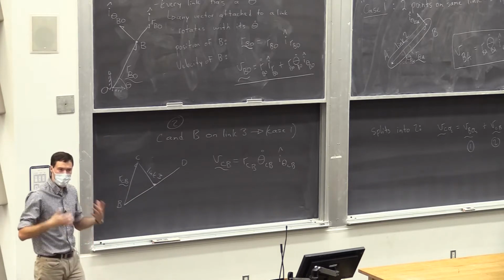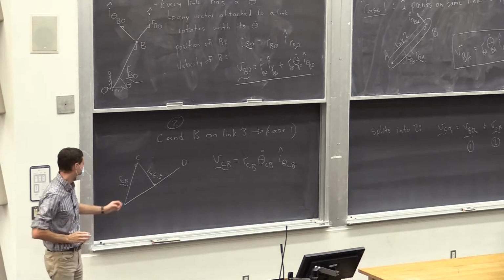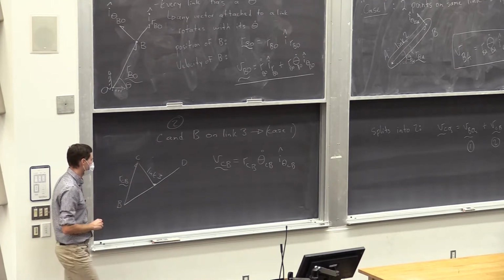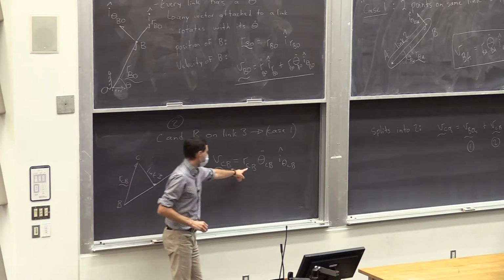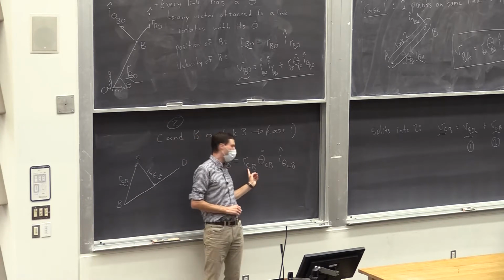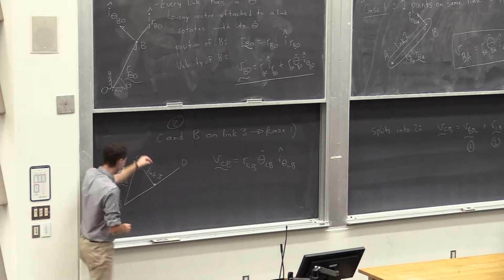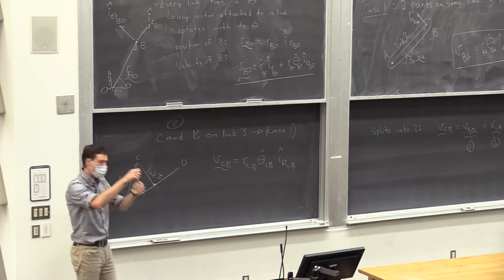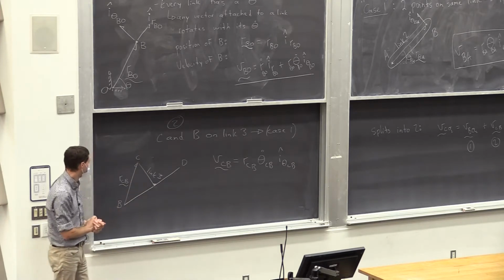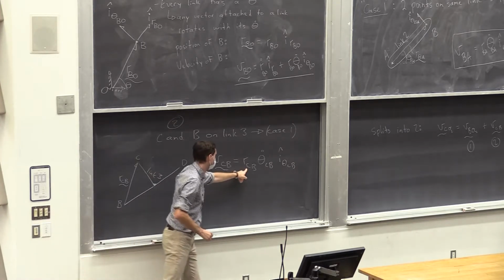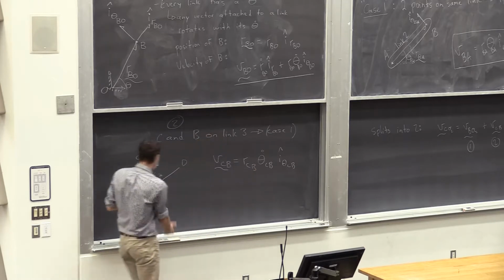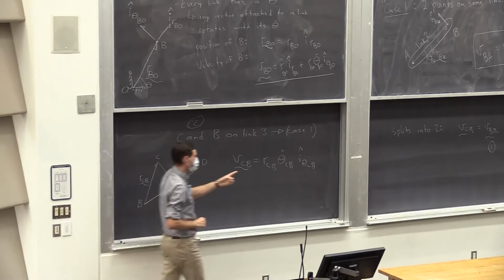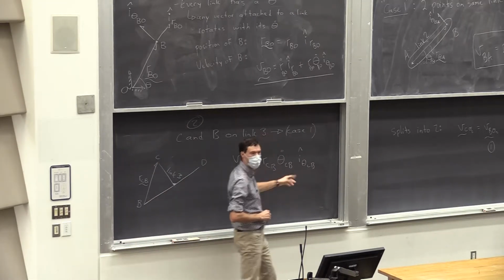And you don't have to do this every time, but anytime you have a weird shape link, until you get really comfortable with them, I suggest you draw this out so you can figure out what's happening. So the length of that vector is RCB, right? So you can measure this distance. If it's a graphical problem and I give you a scaled diagram, get your ruler out, measure that distance on link 3. That's RCB. Theta dot, that's the rotation rate of the whole link. It's always going to be that. Now the last piece is the direction, I theta.